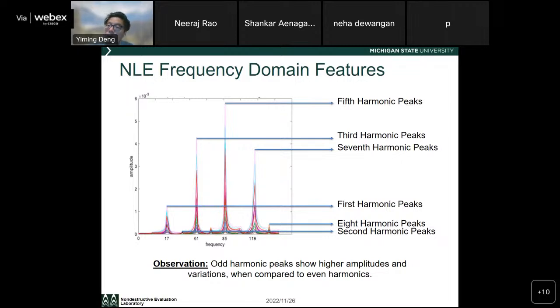And I think the nonlinearity properties of nonlinear NDE methods is something that is still not very well understood. If you look at nonlinear ultrasonics, that's also something that will give you very interesting results if you understand what you're doing in exciting your nonlinearity in your measurement there. So I believe that this is something that will have richer information embedded in acquired NDE signals.